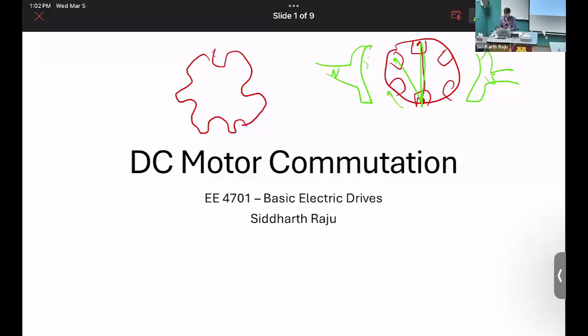Right? So let's say this rotates 10 degrees in this direction. Both these 2 conductors would be on the north pole. Right? So it's not producing the same amount of torque as having them 180 degree diametrically opposite. So that will be the disadvantage. When you look at short pitch winding for the project, you kind of argue and figure out the reason for why people still do it. Once we cover armature reaction after spring break, you'll get an idea of it, right?